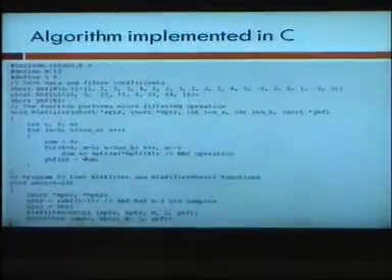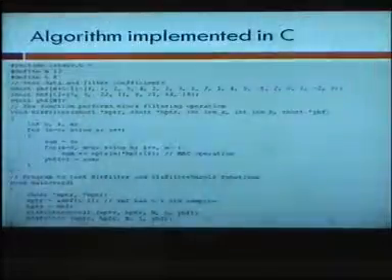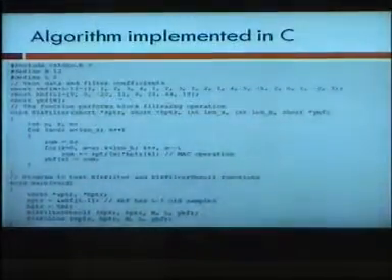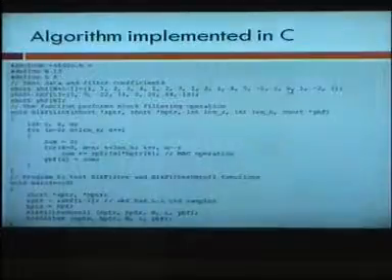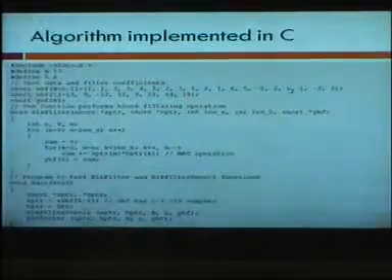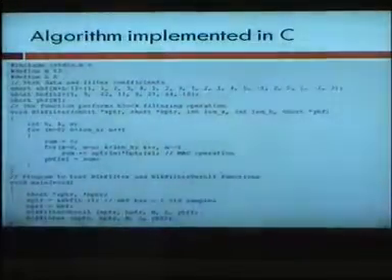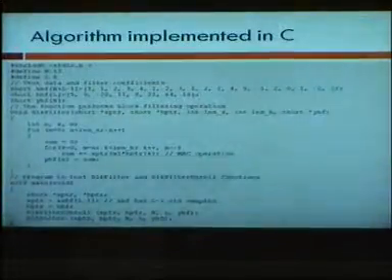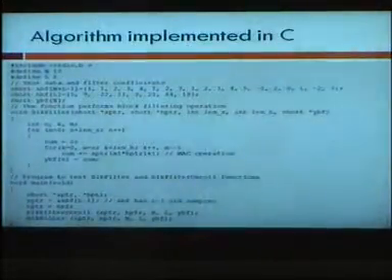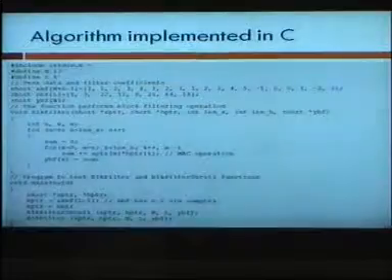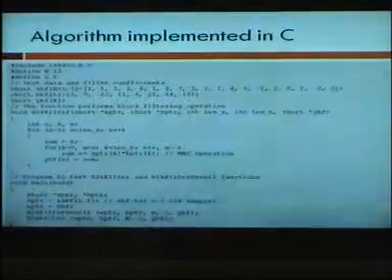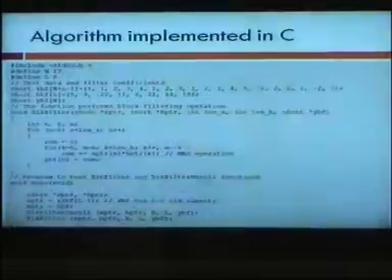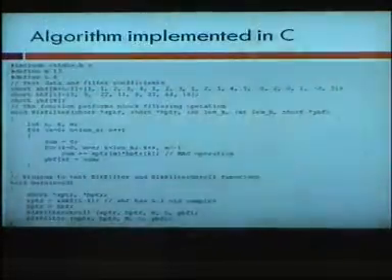Once you are done with 10 of these values, you put this in your y buffer and you go. As you can see, I have taken more values of x just to show that first your x of n is this, then x of n is this. So it's a dynamic buffer which is changing all the time, but usually you don't keep so many values, you just keep the number which is actually required, which is 10. Ten samples are more than enough to keep in this buffer, but you have to update this buffer every time you compute an output value.